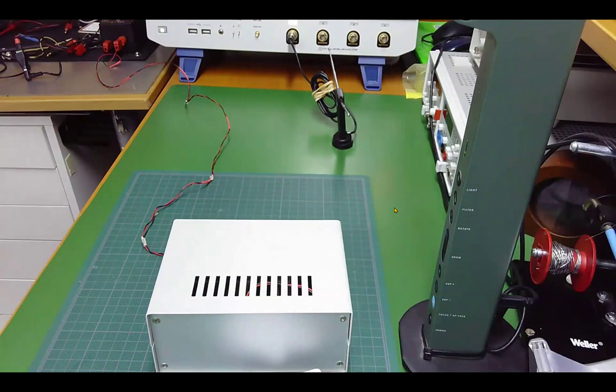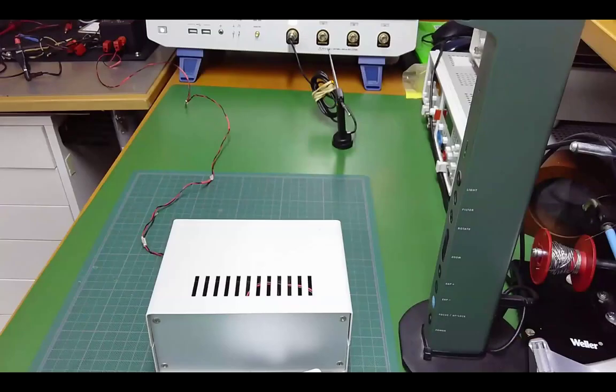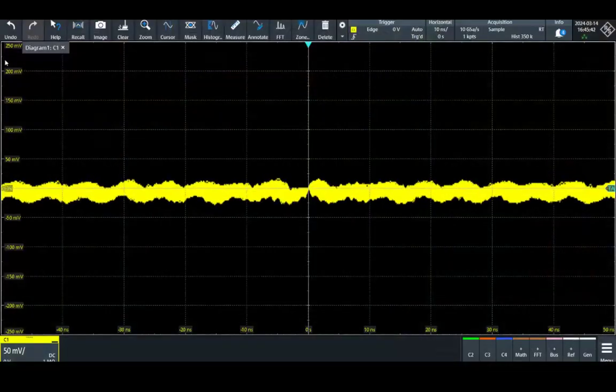But before switching on the device, my recommendation, let me show you the screen of the oscilloscope. This is the output of the antenna. The antenna is measuring electric field from the environment and converting this electric field into a voltage that is going to channel number 1 of the oscilloscope, which you can see in yellow color, with time domain on the horizontal axis.